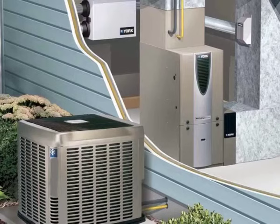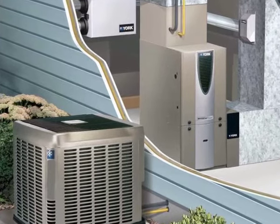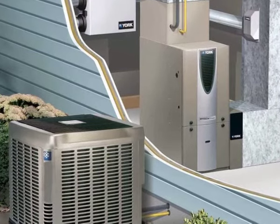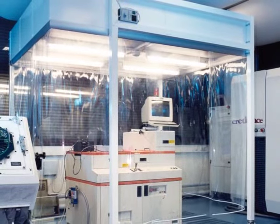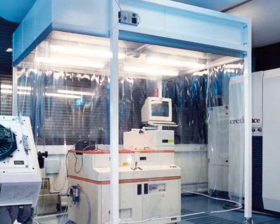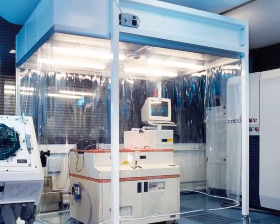An essential part of contamination prevention is the adequate separation of areas of the operation. To maintain air quality, it is important to achieve a proper airflow from the areas of higher cleanliness to the adjacent less clean areas. It is vital for rooms of higher air cleanliness to have a substantial positive pressure differential relative to the adjacent rooms of lower air cleanliness.